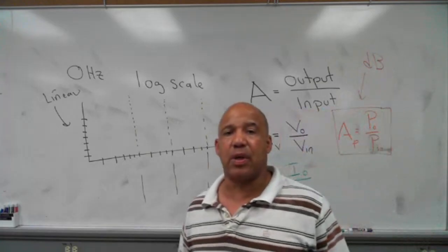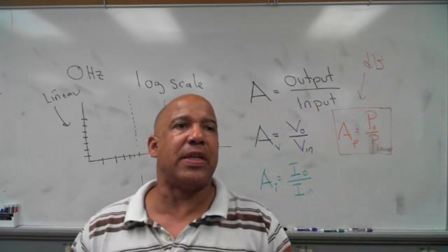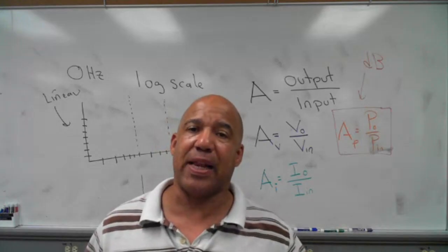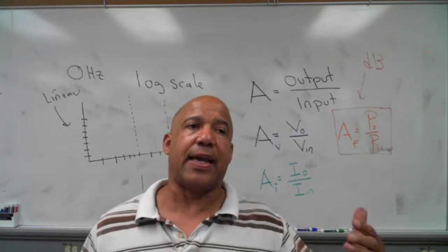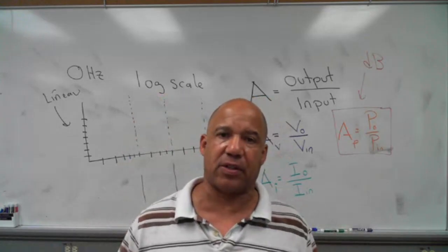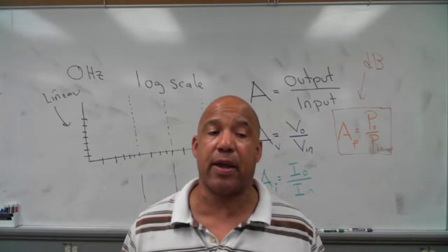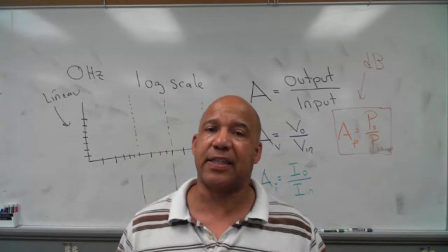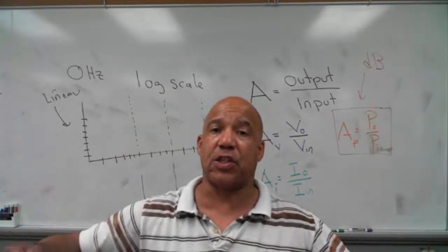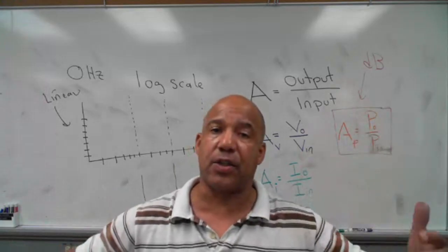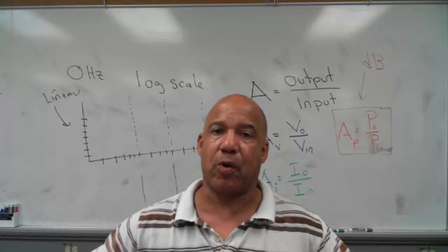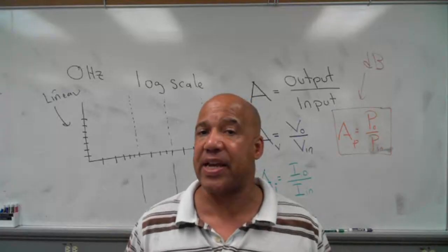Now, what can gain tell us? Well, remember we talked about amplification and magnification? There's a difference between amplification and magnification. What is amplification? Some people will say you put in a small signal and you get out a bigger signal. Well, what kind of signal? You mean voltage or current? Yeah, that's what I mean. Well, no, that's not amplification. That's magnification. If you put in a small signal and get out a larger signal, but the power in and power out are the same, then you don't have amplification.